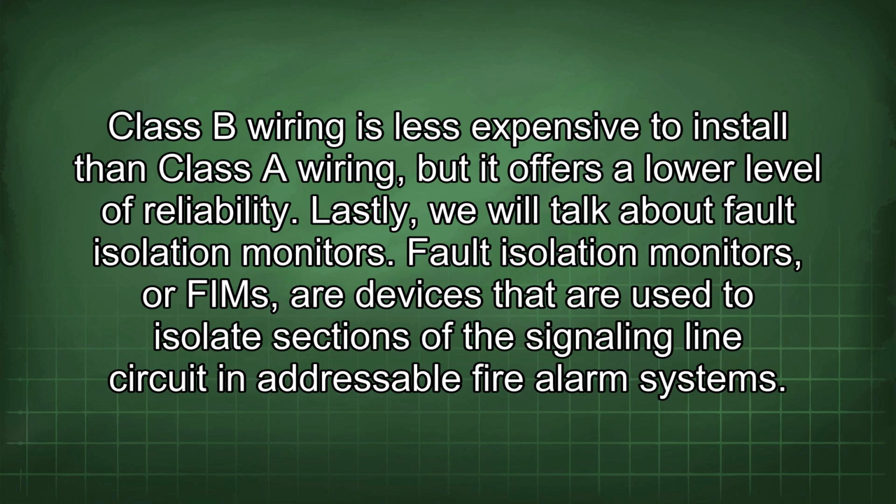Lastly, we will talk about fault isolation monitors. Fault isolation monitors, or FIMs, are devices that are used to isolate sections of the signaling line circuit in addressable fire alarm systems.